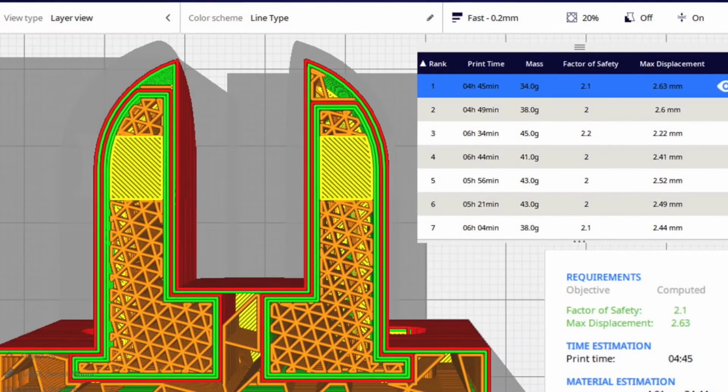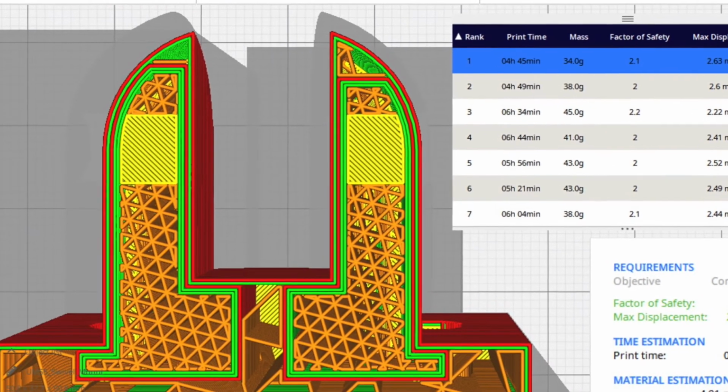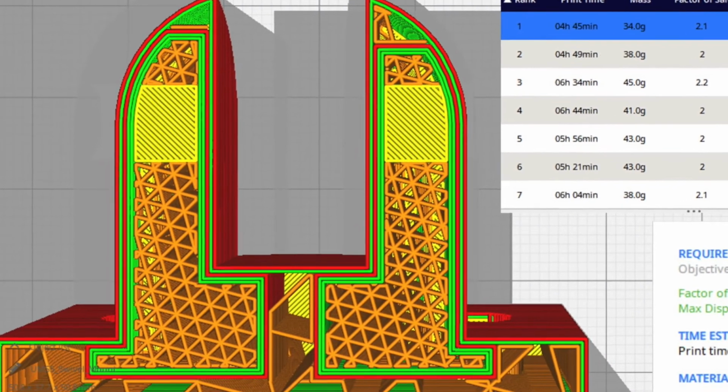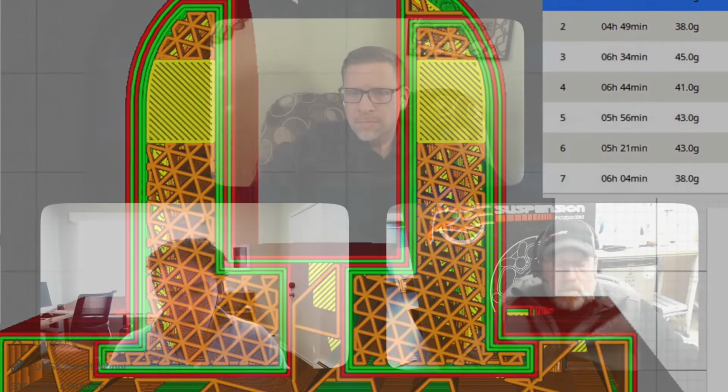You have a big geometry and you can bring in another piece of geometry and ask Cura to locally modify slice settings based on this other geometry. SmartSlice takes advantage of that and will put these little modifier meshes in there and locally tweak slice settings to make parts stiffer and stronger just in this certain volume, which is what it did automatically for that piston tray. Every time you have the diameter change, it inserts a new mesh there and increases the thickness. Now all of a sudden you have a part that survives, but you're not increasing the print time drastically. Actually, it turns out we reduced the print time.